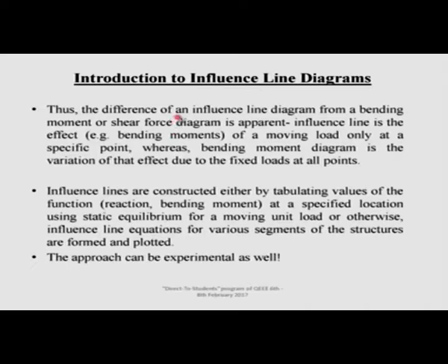So, the difference of an influence line diagram from a bending moment or shear force diagram is apparent. Influence line is the effect, that is the bending moment, of a moving load only at a specific point, whereas the bending moment diagram itself is the variation of that effect due to the fixed loads at all points. This is the difference from the bending moment diagram and shear force diagram. Although the book spent a lot of time over it and tries to tabulate the difference sometimes, making the student feel that this is a very basic quantity of interest.